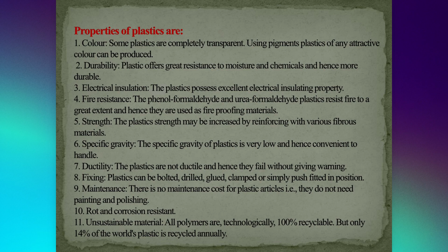Fire resistance. The phenol formaldehyde and urea formaldehyde plastics resist fire to a great extent and hence they are used as fireproofing materials. Strength. The plastic strength may be increased by reinforcing with various fibrous materials. Specific gravity. The specific gravity of plastics is very low and hence convenient to handle. Ductility. Plastics are not ductile and hence they fail without giving warning.